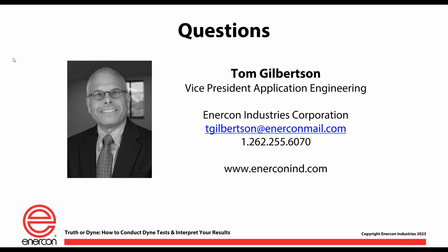Tom, we've got two questions here on wider films. I'm going to kind of combine them. The first part is, for a wide web, what's the best way to determine the Dyne level using Dyne test solutions and swabs? And secondly, can the electronic devices be used to measure BOPP film 6,600 millimeters in width? How many measurements could determine the Dyne level?